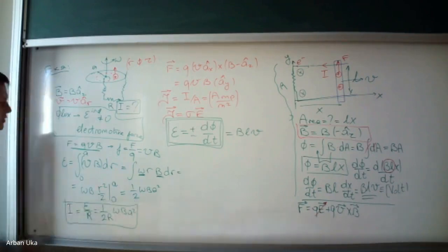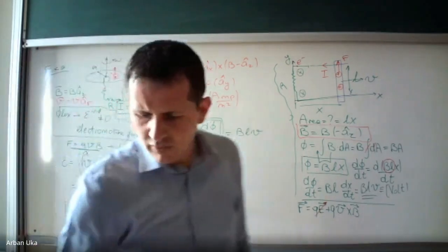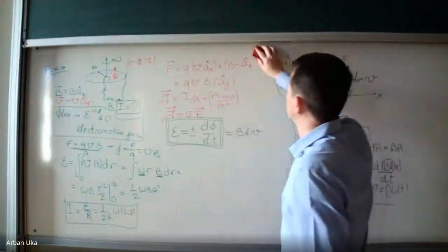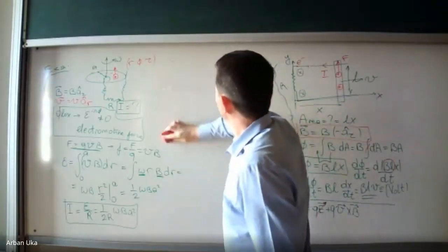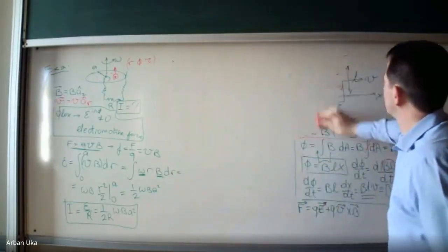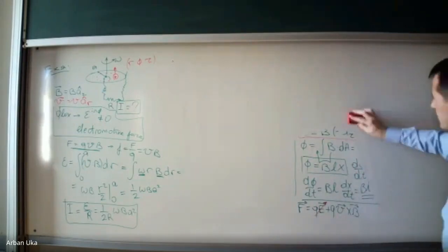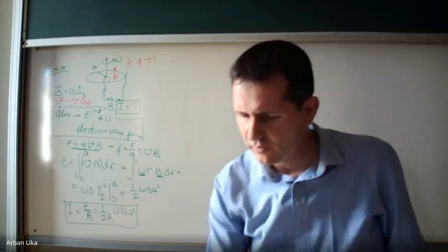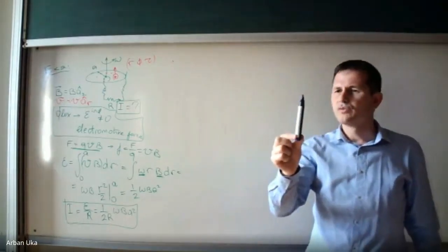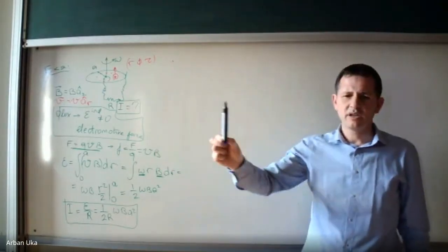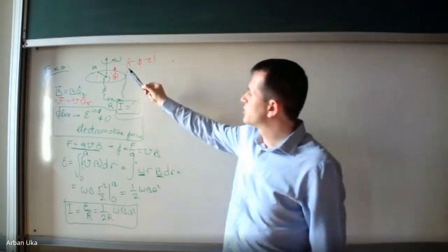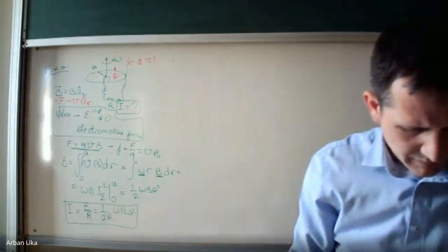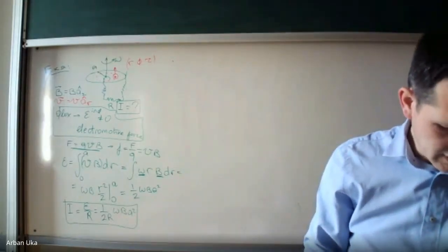Here, we notice that if omega, the rotational speed, is higher, we are going to get a larger current. Okay, so we found the EMF for two different configurations. In the configuration that we just erased, what did we have? We had a conductor which was moving, changing the effective area of the circuit. Here, we are not changing the area of the circuit, but we have a rotating disc as shown in the figure.